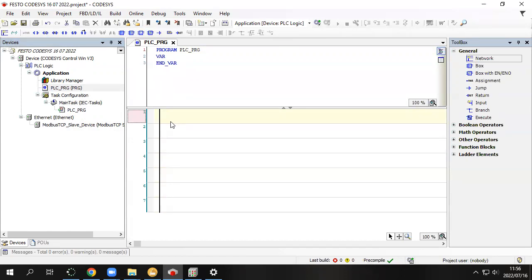Okay? And then we use variables, guys. When on a small PLC, the basic PLCs, you don't use variables. You just drag I1, you write a code, I2, Q1, and stuff like that, but not here. Here we write variables, and the nature at which we are writing the variables is like this.